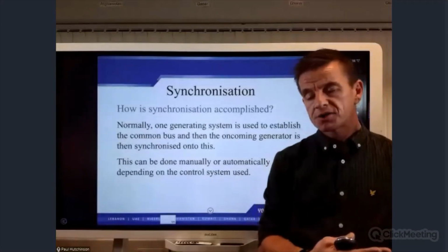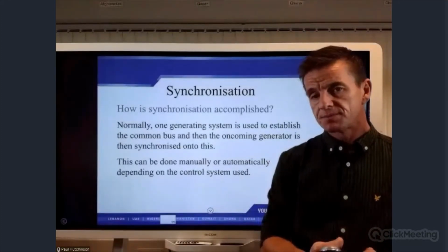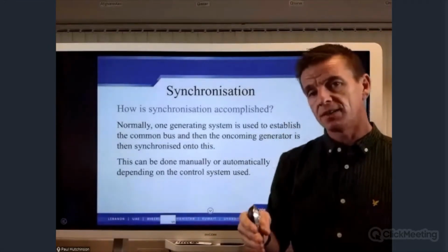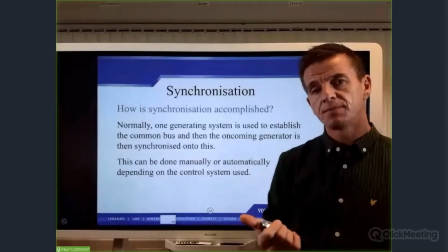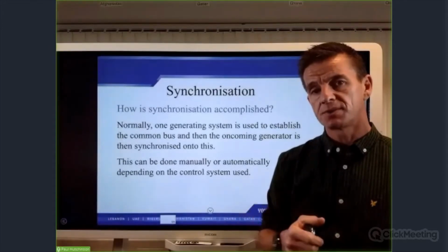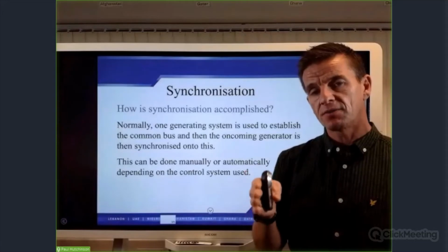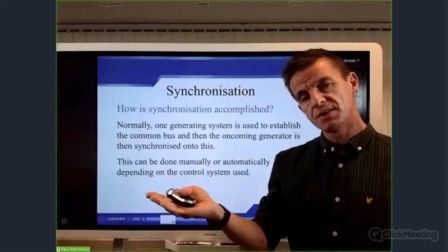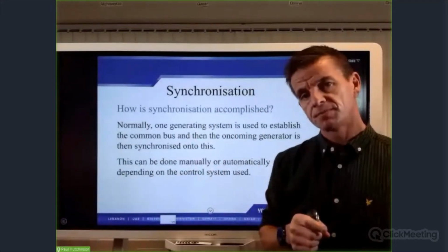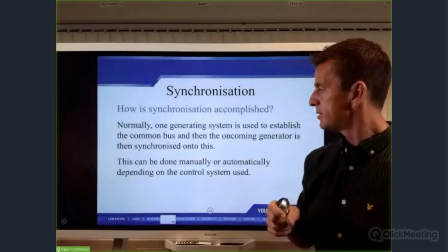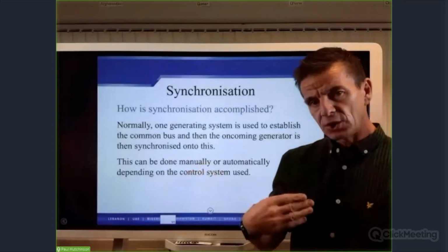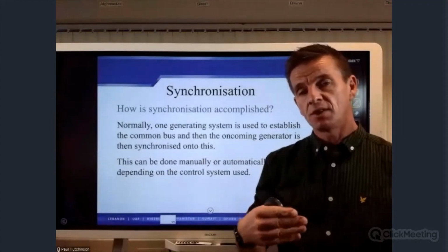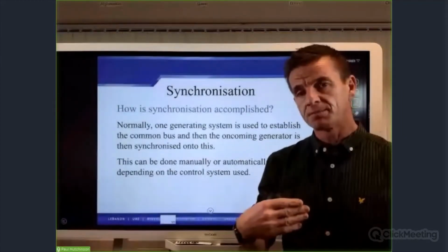So, how is synchronization accomplished? Well, normally we'll already have one system online, whether it's a generator or the mains. We always have to have a voltage there as a reference for the other sets to synchronize to. Again, in the old days, depending on how old you are, some of these would have happened years back.